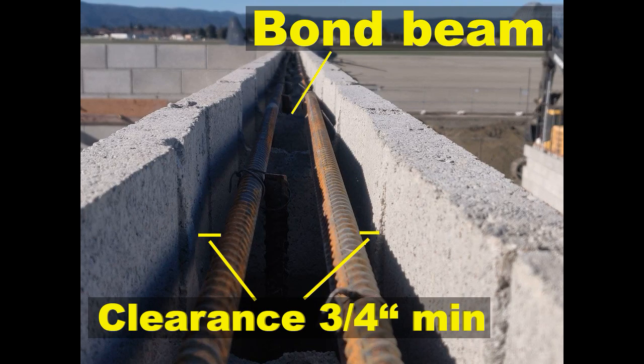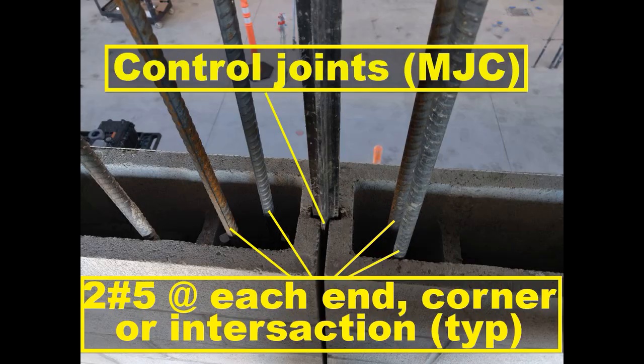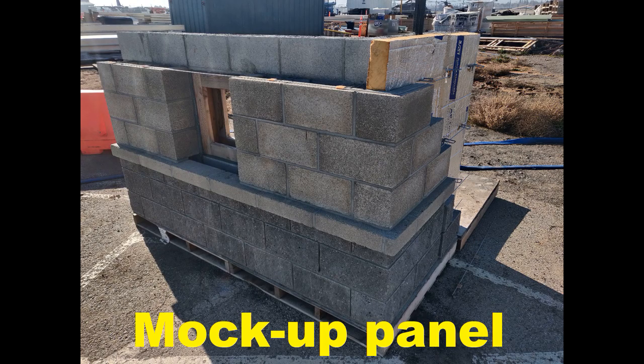Include a masonry bonded corner and a bond beam corner. When the panel represents reinforced masonry, include a 2 by 2 foot opening placed at least 2 feet above the panel base and 2 feet away from all free edges, corners, and control joints. Provide required reinforcing around this opening as well as at wall corners and control joints.